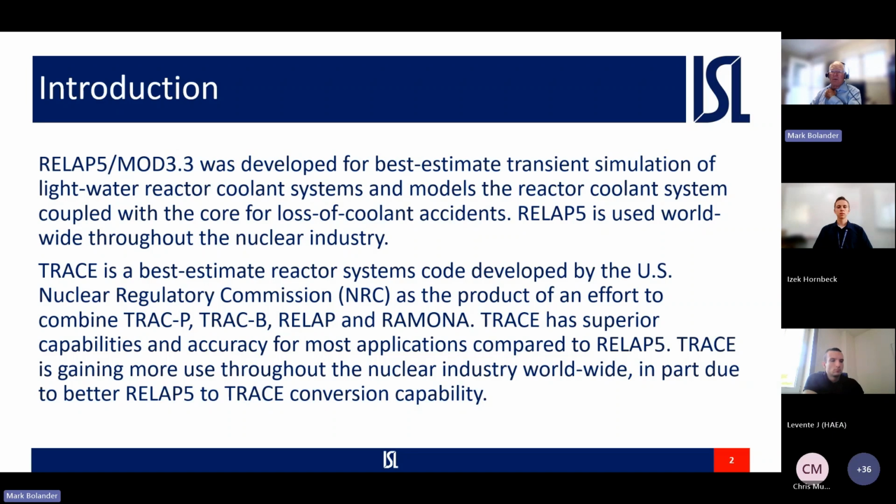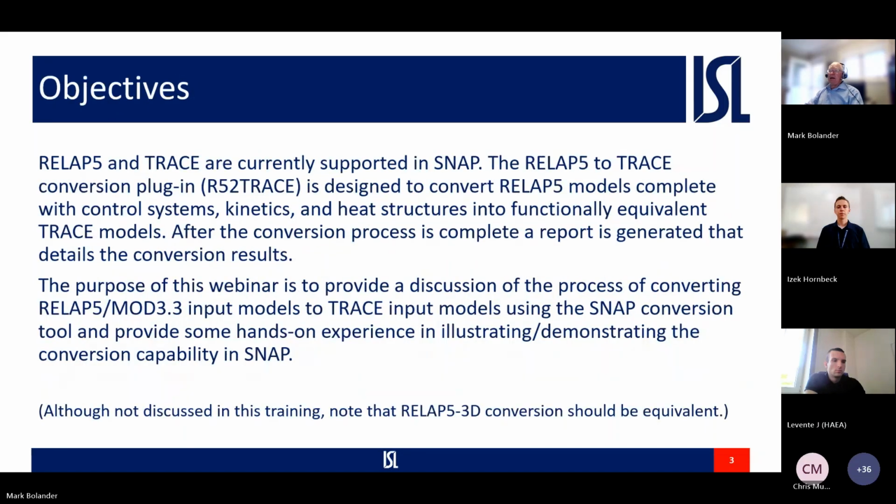TRACE is gaining more use throughout the nuclear industry worldwide, in part due to a better RELAP5 to TRACE conversion capability. So our objective today is to look at the conversion process from a RELAP5 Mod 3.3 model to current TRACE.